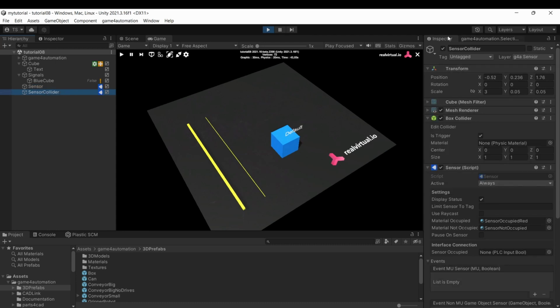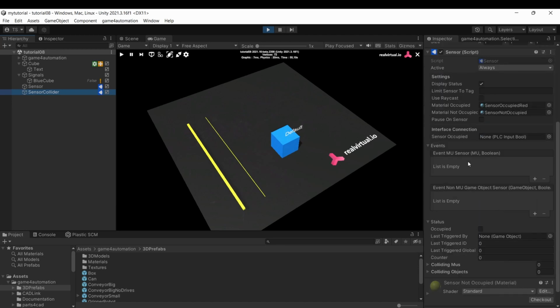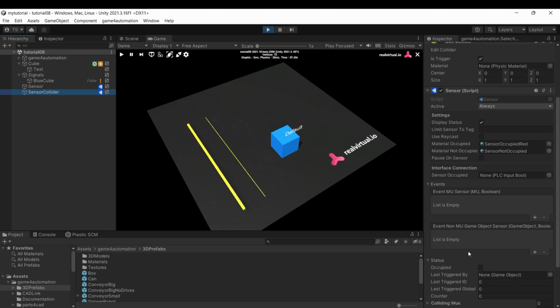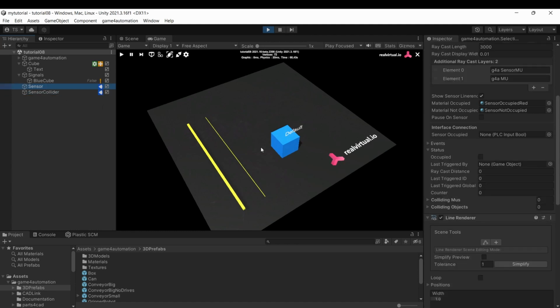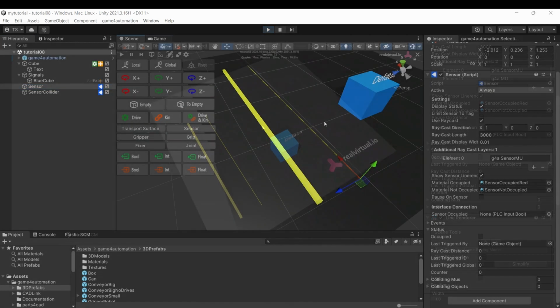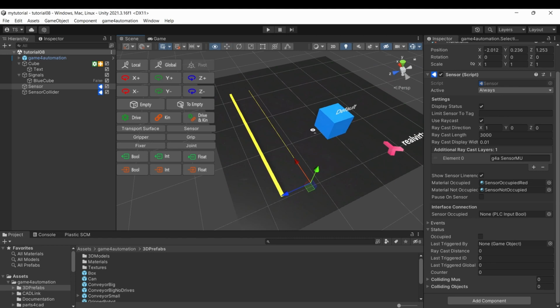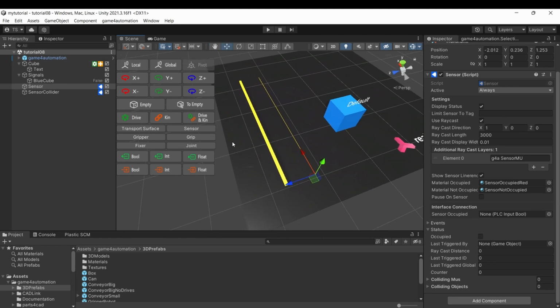If you're using collider-based sensors, please always use box colliders. Using mesh colliders, especially against other mesh colliders, could create flickering sensors due to limitations in the physics engine. So that's also the case why raycast-based sensors are preferable in most cases. What about collisions between parts?